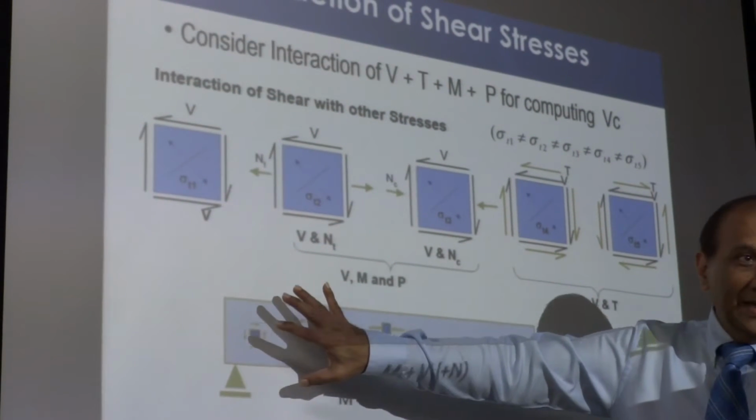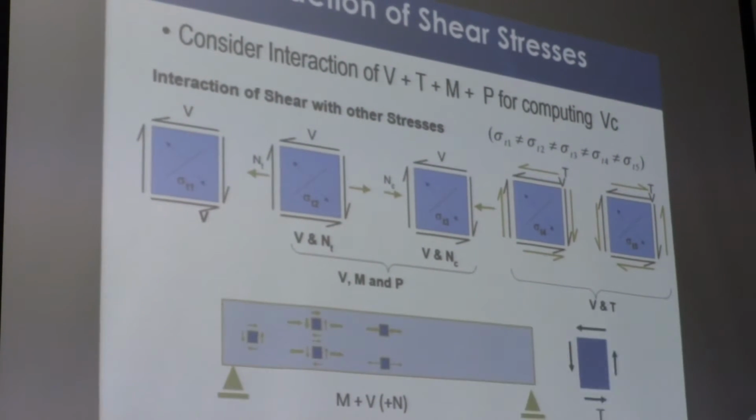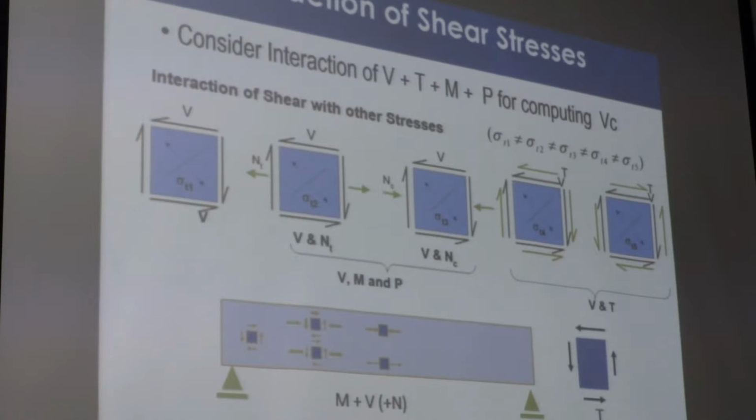So you can imagine that this variation will change along the entire beam. So no single value of the shear principal direction can be calculated based purely on shear, because the axial bending moment is also changing the tension that you are trying to provide for shear, correct? Because that is derived from principal stress concept, Mohr's circle. So the angle of the shear, amount of the tension and angle will change.